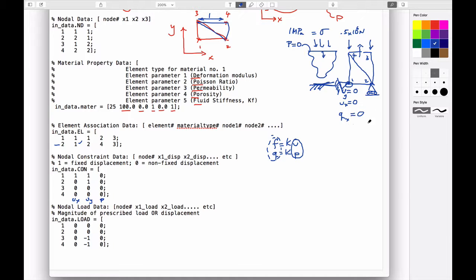So if the fluid pressure is not defined and it's a boundary, then the flux is defined as 0. And so this means the flux, since it's this term here, and this is also flux. And for the top ones, no displacement is prescribed, so by definition a force is prescribed. That force could be 0 if it's an interior boundary, but it doesn't need to be 0, it can be a number. So a force is prescribed, and if you look here, the force in the minus y